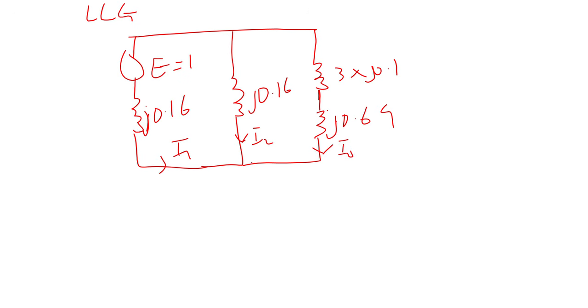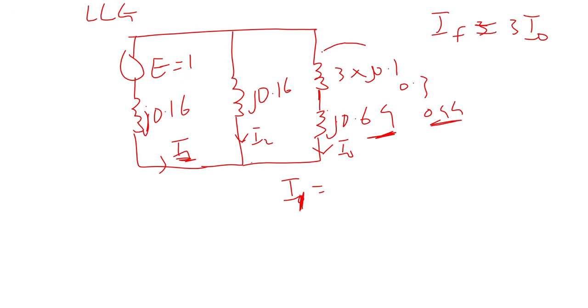And we know basically that from here, I0 will end up, because my fault current for line to ground also is equal to 3 I0. So I basically need to know I0, right? What will be I0? First, I need to know I1 first before I can calculate I0. I1, this current is going to be, this will give me 0.3. So adding that to this, I'm going to get 0.99, right? So this whole thing is 0.99.